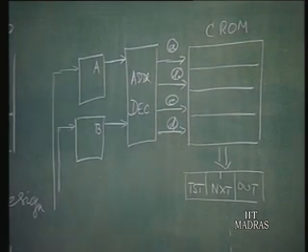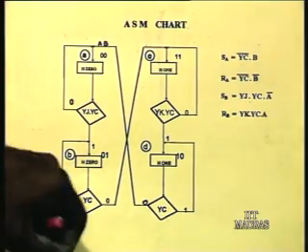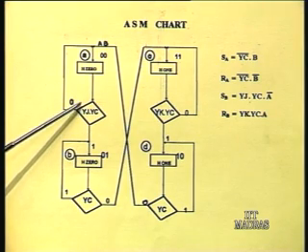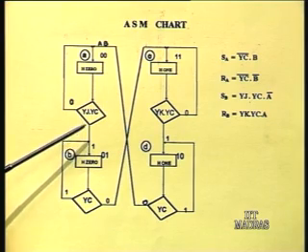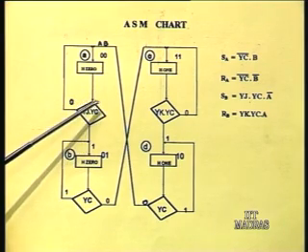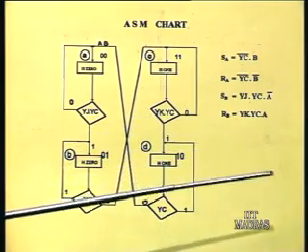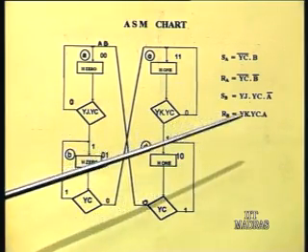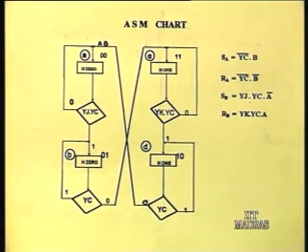And if you see the ASM chart, we have reduced the next state to only 2 next states. One we call a false next state, the other a true next state. It is possible that in any practical problem there can be more than 2 next states, but everything can be reduced to always only 2 next states, right, that is okay.